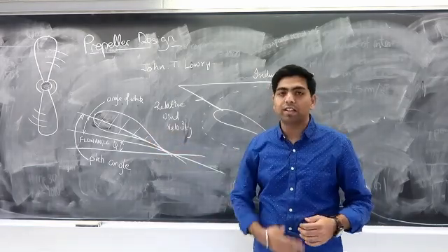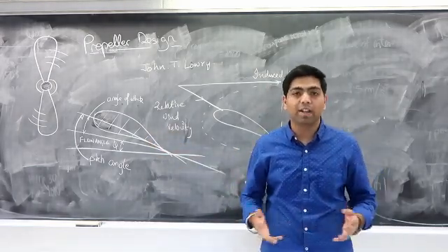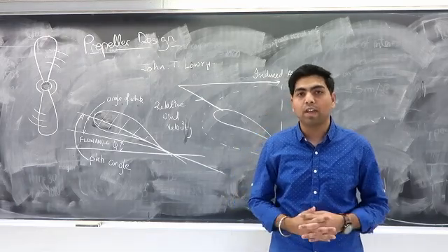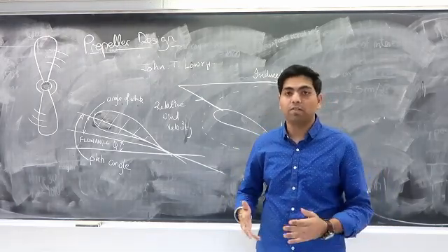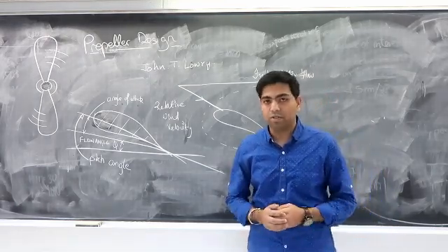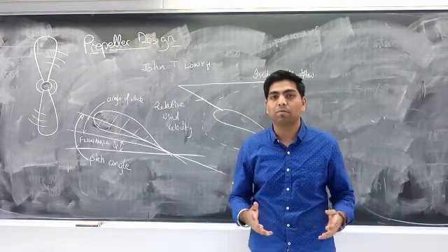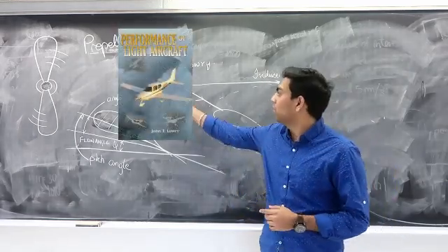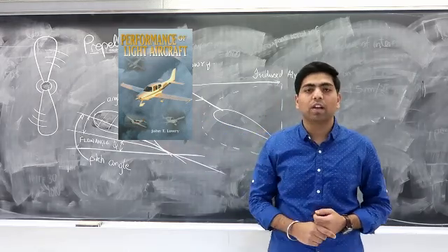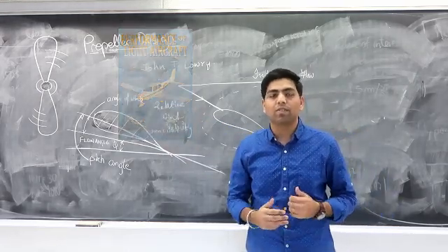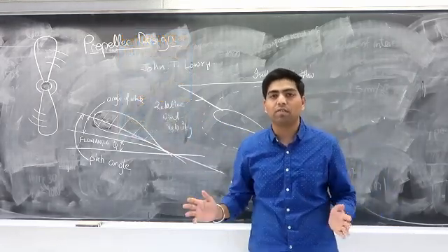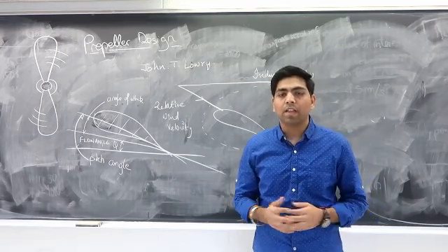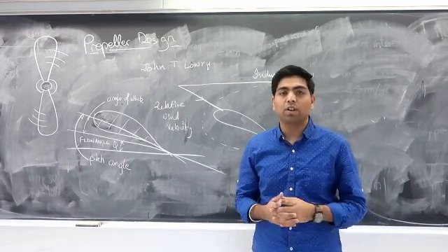And your angle of attack is set by knowing the maximum L/D ratio. From aerodynamics, we know that it is a certain positive value, and that value was found by our calculations. We referred to this book called The Performance of a Light Aircraft by John T. Lowry, and we had certain calculations. We found the performance of around 10 different airfoils using XFOIL,